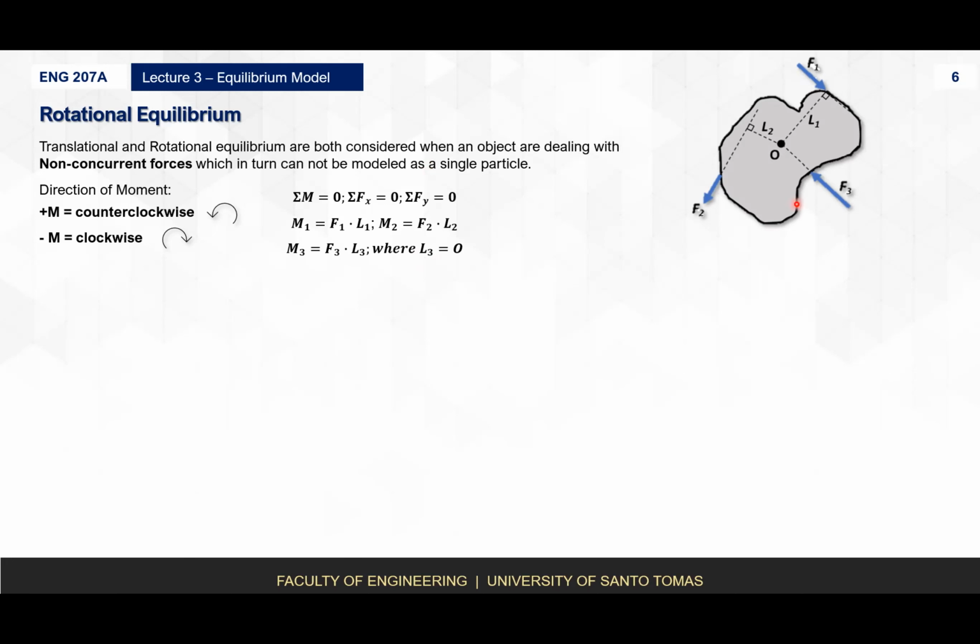So this one is just referring to this figure here. You can see that forces 1 and 2 have moments, and unfortunately for force 3, it doesn't have a moment because it doesn't have a distance to lever it with. It has, however, depending on which direction you're looking at, it could be a horizontal or simply a vertical force being applied to it. Now, unless we have moment at 0, wala na kagad yung forces na yun kasi it's not considered; you're only dealing with F1 and F2. Next.